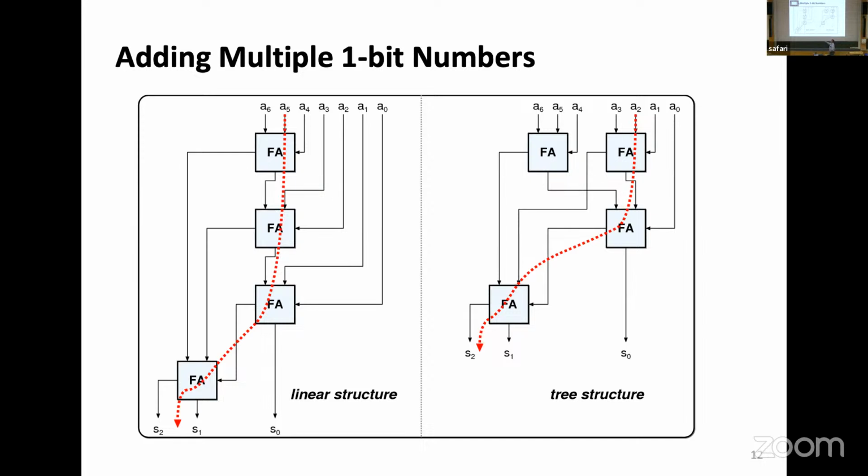Now, we looked at this. And then we realized there's also this version. And if you examine it a little bit, it's not like we have to memorize it, but you see that we do some parallelization. The first full adder sums up A6, A5, A4, and the second one sums up A3, A2, A1. We generate the sum here, and we have A0, we add that, so that's my least significant bit, and the same carryouts come here, and I add them up. They both will do the same. Do we agree? Yes? Good.